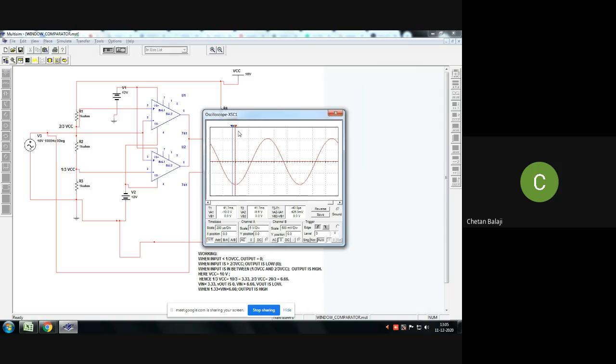I'll make only the input. Okay, measure the input. You take this measuring instrument, you move along with this. You can see 10 volts here, 10 and minus 9.6. That is okay. Plus 10, minus 10, the swing happens. Since I'm giving VCC as 10 volts here, obviously this should be my 10 volts. I'm getting that value here. So I'll make this output also as AC.